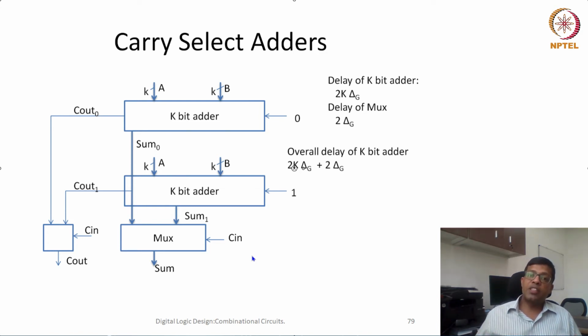So this is a very general optimization technique which can be used in designs, as well as in coding algorithms or wherever. The idea is that if we are able to do two copies and then finally choose which one to select, it can reduce the delay, but it increases our design effort. It is also increasing the area or cost. But delay can be minimized.